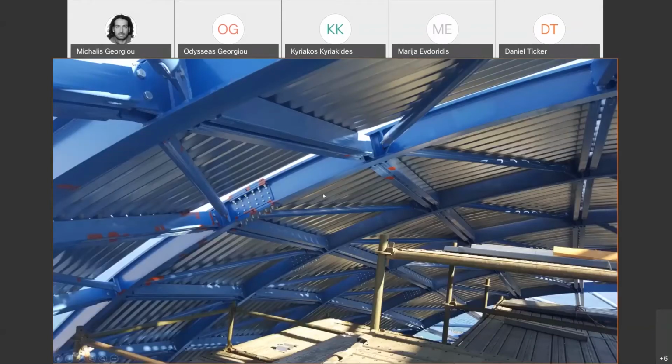So inside the impressive image that I showed before, there is an even more impressive construction, which serves two main purposes. The first one is to bridge the opening of approximately 30 meters between the main concrete structure of the building, and the second one is to carry the loads of the shell structure.